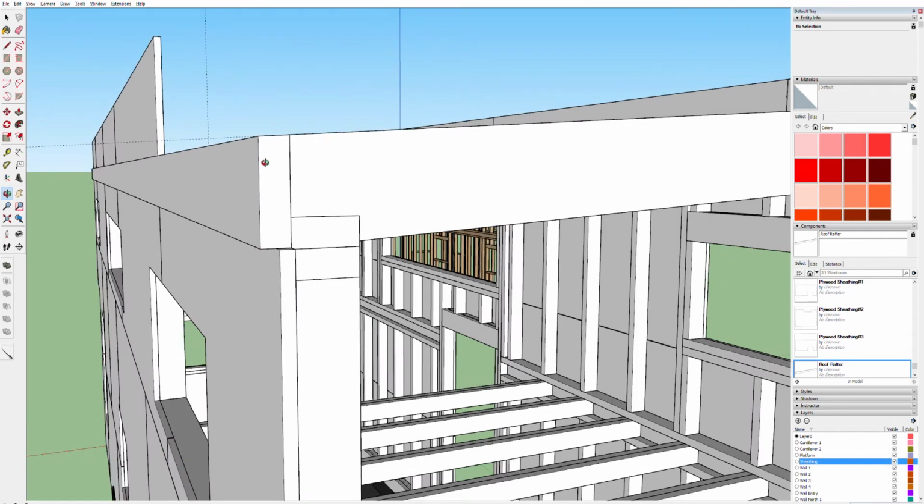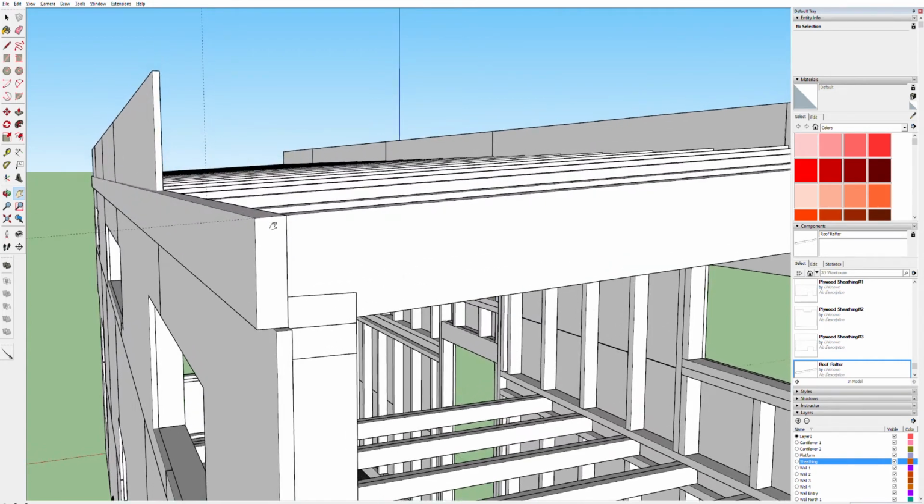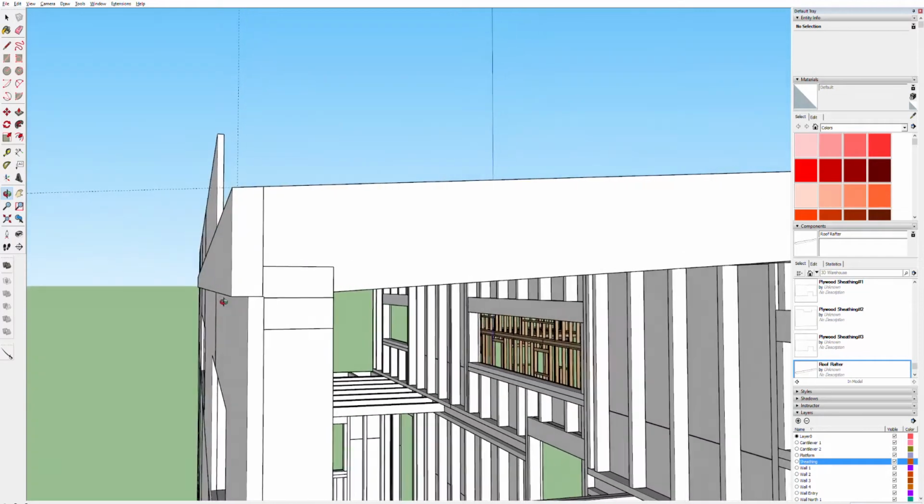And then we're going to have some piece of drip edge flashing, and that's going to be nailed down into the roof sheathing. Then it's going to come down, make a 90 around here, and flare out a little bit down here, and then our roofing is going to go on top of that. So when water sheds down the roof, it's going to shed off the drip edge and then drip out,